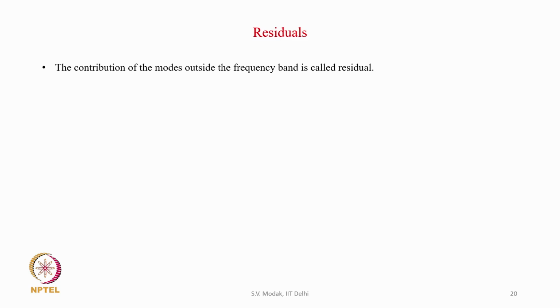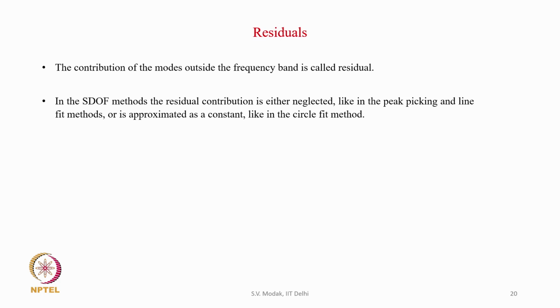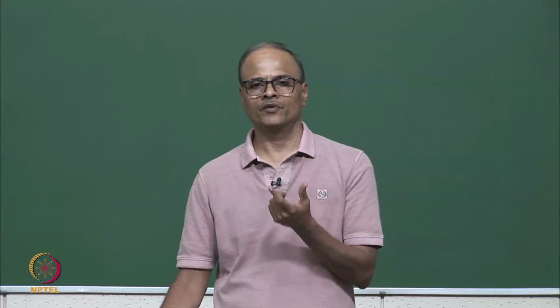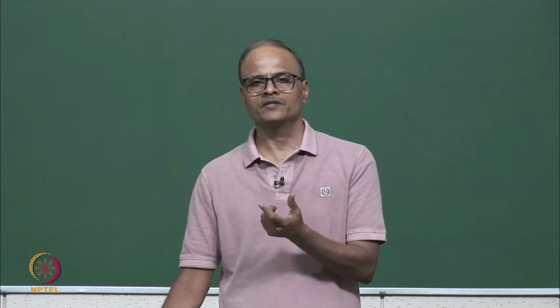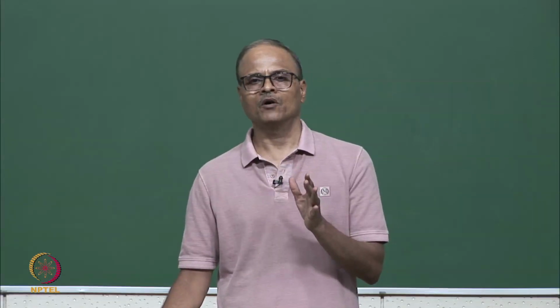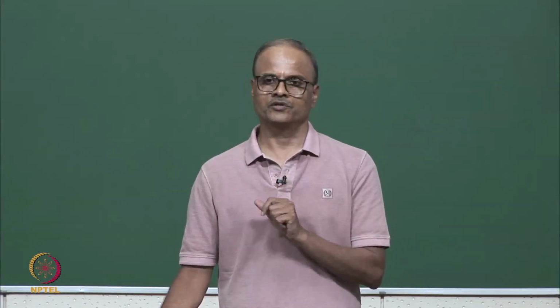The residuals are nothing but the contribution of the modes outside the frequency band. We saw that in the single degree of freedom methods the residual contribution is either neglected, like in the peak picking method and the line fit method, or is approximated as a constant, like in the circle fit method. So, the residual contribution of the modes which are outside the frequency band that has been chosen for analysis is either completely neglected or assumed to be constant.